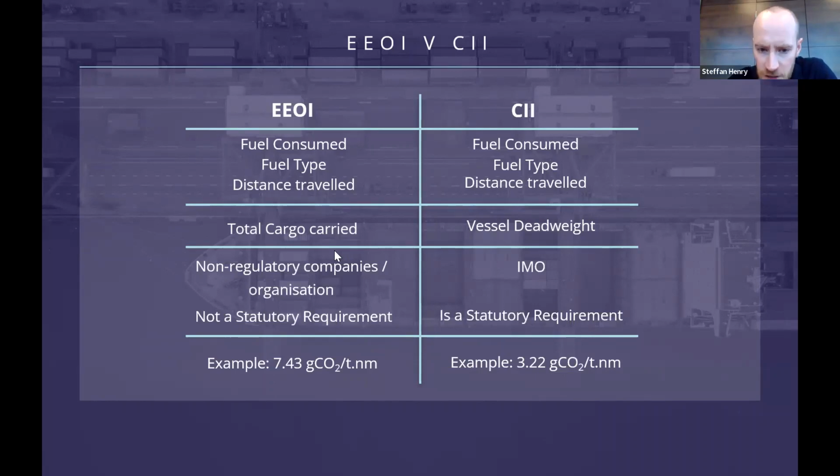Here we can see an example difference of the attained EEOI and the attained CII score for a vessel. In most cases, the attained EEOI will be higher than CII because CII assumes that the vessel travels fully laden all the time, which is not true.